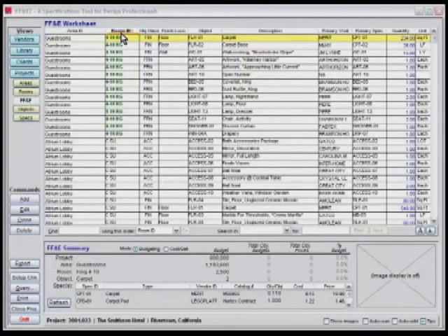The FF&E Worksheet is a little different from other screens, primarily because it has a very simple data content. Although we obviously can see a lot of data here, the only thing you enter or change on the worksheet is the answer to that question: what goes where and how much. Each row in the data list represents an occurrence or usage of an object in a room, and the only data that really exists in the worksheet itself is in the room ID and finish location columns, the object column, and the quantity itself.